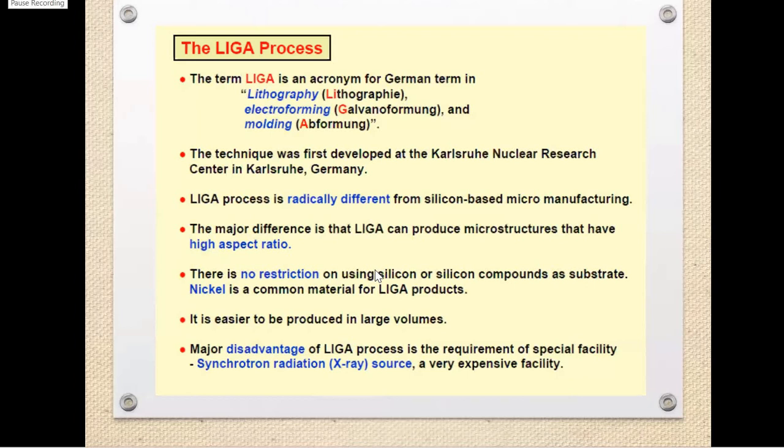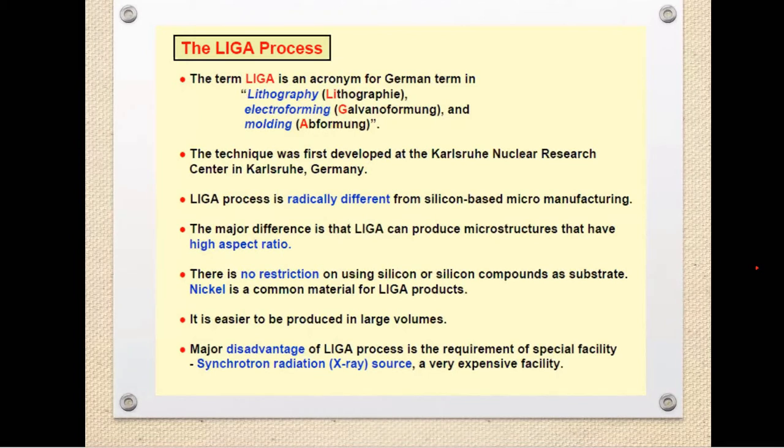Microstructures. So this is the third one, that is the LIGA process. Basically, we have discussed that things like bulk manufacturing and micro machining involve the production of microelectronics or microstructures for micro fabrication purposes only. We have also discussed the drawbacks, like the low geometric aspect ratio we have with bulk manufacturing and surface micro machining, and these both are usually based on silicon based materials. So in order to overcome these drawbacks, another process comes, that is the LIGA process.